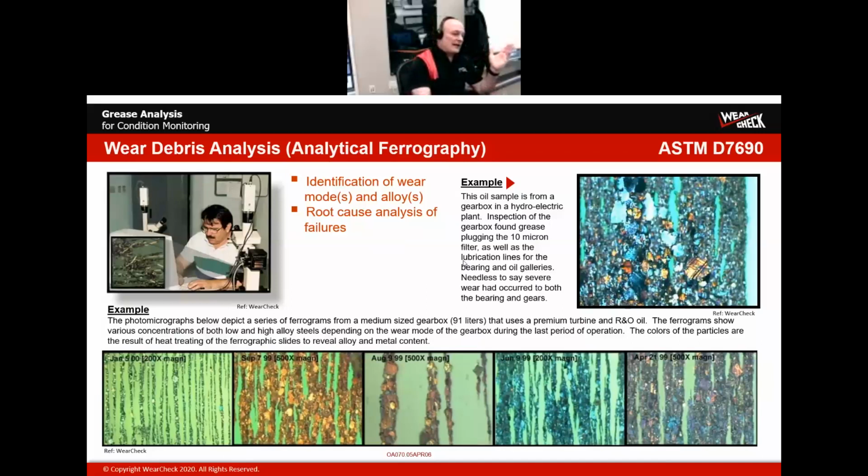The slide will have wear particles. The largest will be at the entrance of the slide and the smallest particles at the exit of the slide. Also, the ferrous particles are lined up perpendicular to the magnetic field that is used to pull them and fix them onto the slide. If you see particles that are sort of randomly distributed across the slide, you know they're non-ferrous. You can also use a heating plate to heat treat the slide so that you can determine something about the metallurgy.